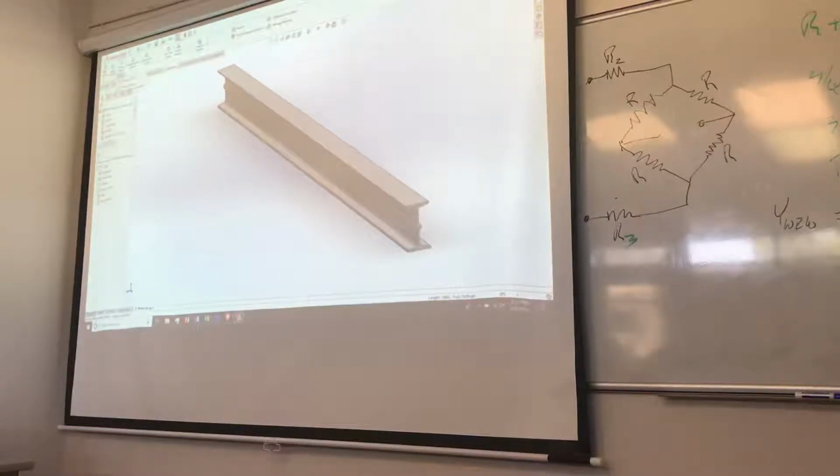So let's go apply displacement constraints. You notice we got very little choices here. We got fixed geometry, so okay. I don't really want fixed geometry, but immovable is not a bad choice. And you notice the only thing I can pick on here is this little symbol over here, which tells me the only thing I can apply my displacement constraints to is the joints. I can't apply them anywhere else. So if I want to apply them in some particular place, I have to make a joint there to be able to do that.